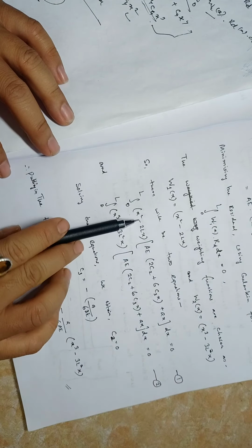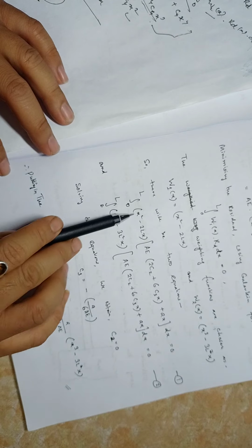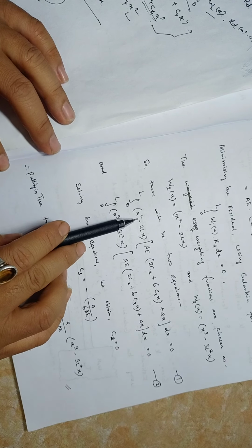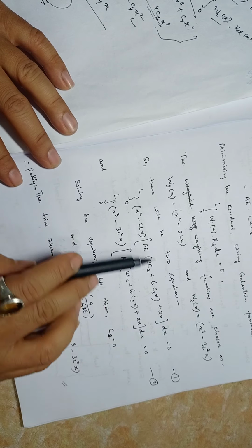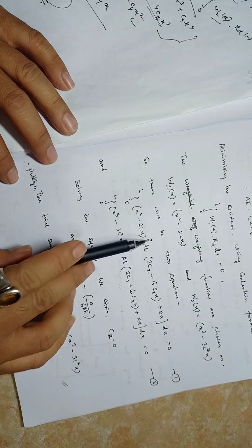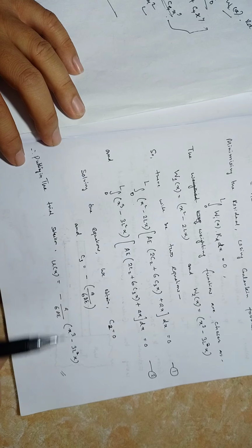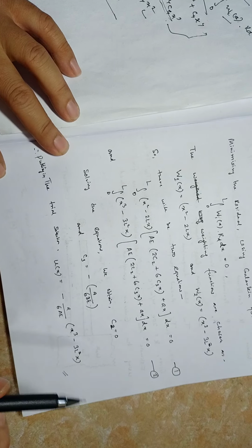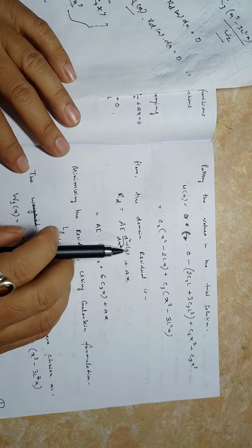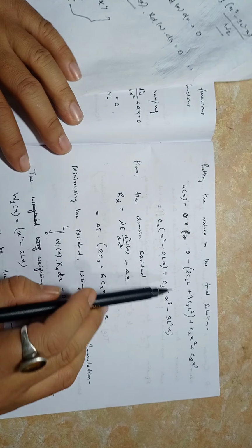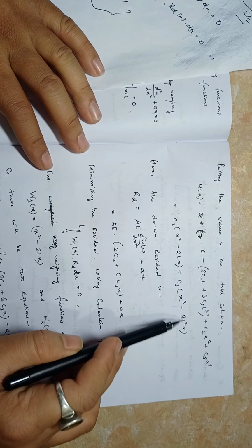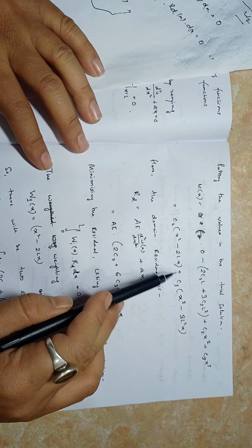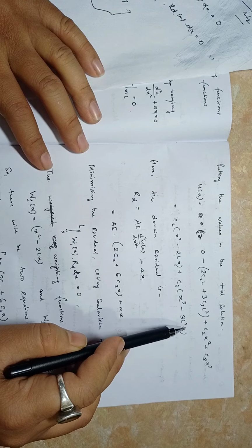Now you see C3 is minus a by 6AE, but you have to integrate them, multiply all the terms, integrate them, put L and 0 in place of x, and then solve both the algebraic equations to get these two constants. So it is minus a by 6AE. Putting this in the trial solution, C2 is 0, so that term will go, and C3 is minus a by 6AE, so put that here and take the minus sign inside, so a by 6AE multiplied by 3l square x minus x cube. So this is the final expression.